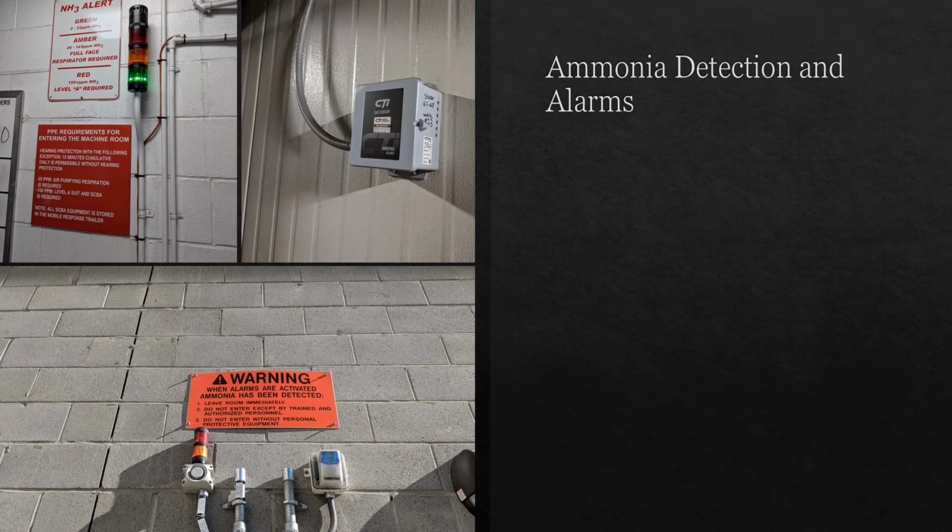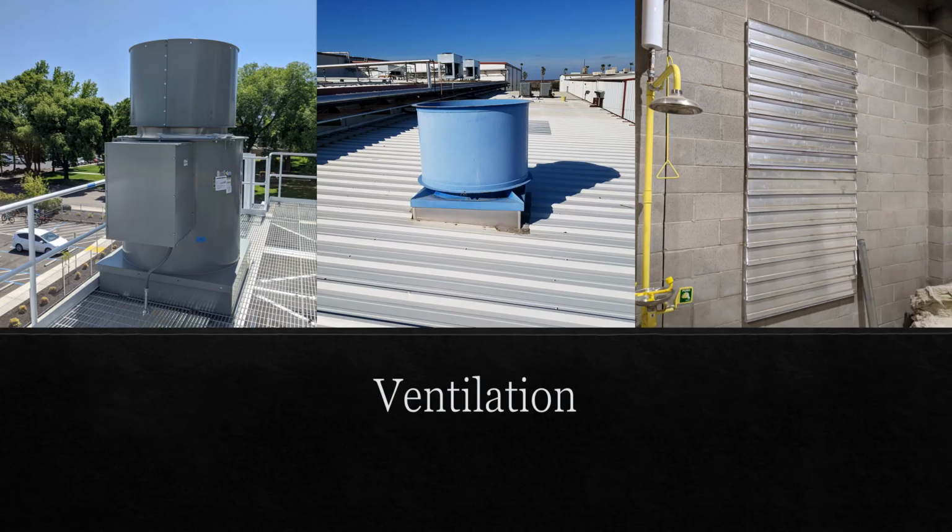Standard 9 specifies that audible and visual alarms are required both inside and outside the machinery room. There is no requirement in Standard 9 to provide detection outside the machinery room, although Appendix A warns that ammonia detection may be required in areas other than machinery rooms by the building code, fire code, or mechanical code in effect at the time of installation. Section 7.3 concludes by addressing machinery room ventilation.